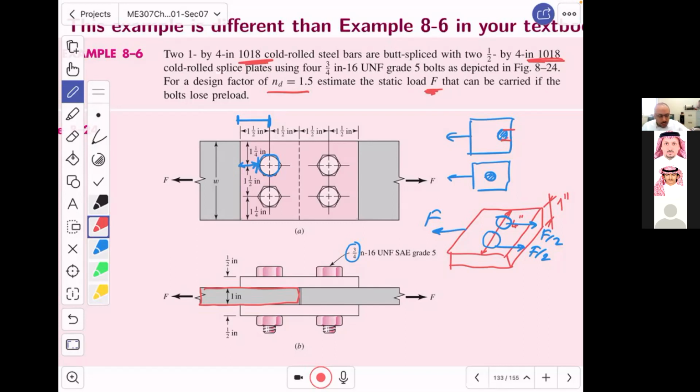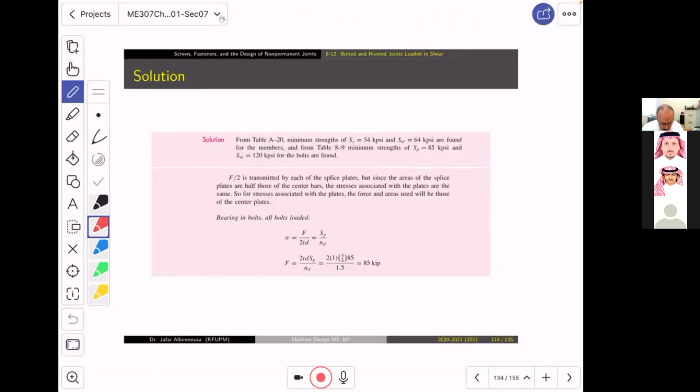big force. But if the material with respect to that mode of failure is weak, it will tell you, no, don't apply a lot of load. And thus, you will say, okay, I have like 5 loads, and I will pick the lowest. Why the lowest? It's very simple. Because you need to secure the joint from all kinds of failures. And that's what we are going to do. Okay? All right. So the first thing is this.